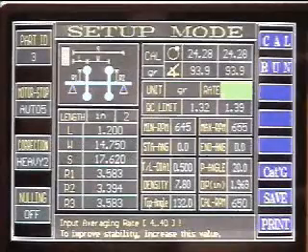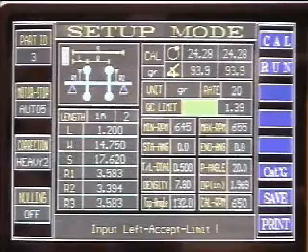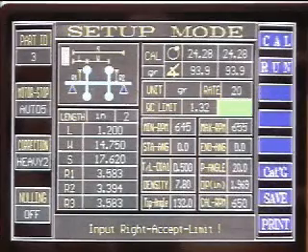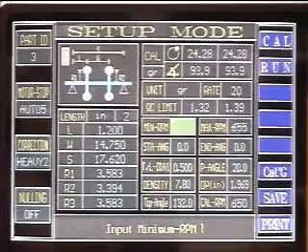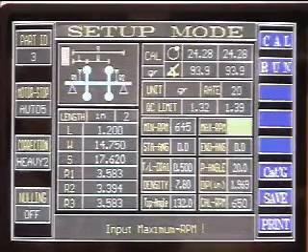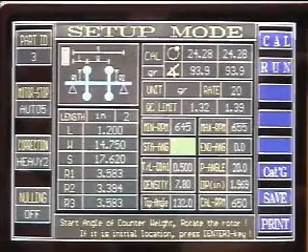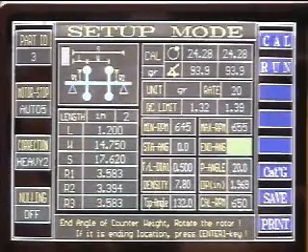The rate parameter determines how many samples per revolution are taken. The QC limit is the part balance tolerance for left and right planes. Below this is the minimum and maximum RPM values for accepting readings. Starting angle and ending angle refer to the angular values for the crankshaft counterweights for inline crankshafts. For all other parts, these should be set at 0 degrees and 0 degrees.